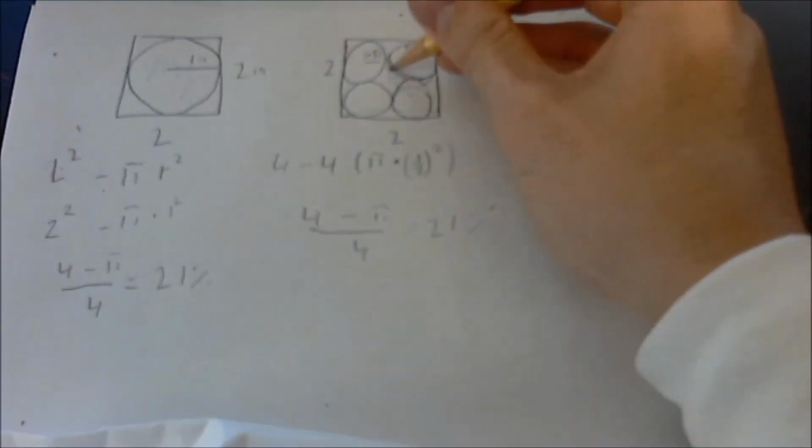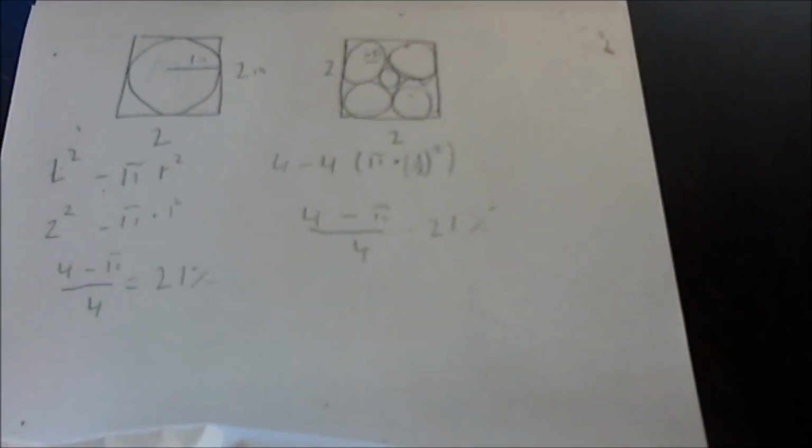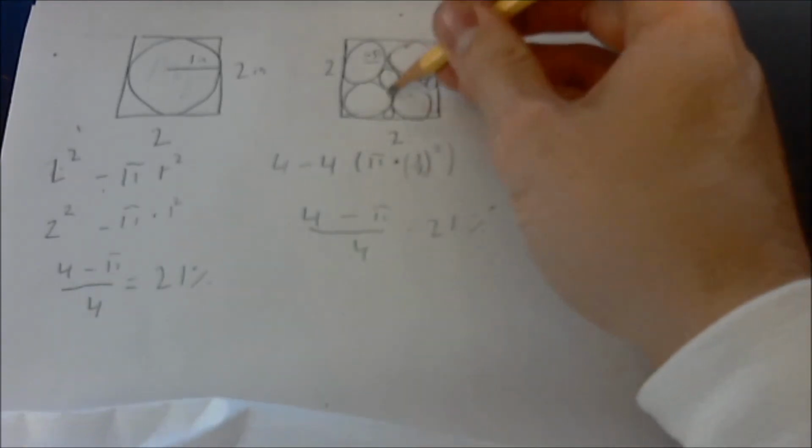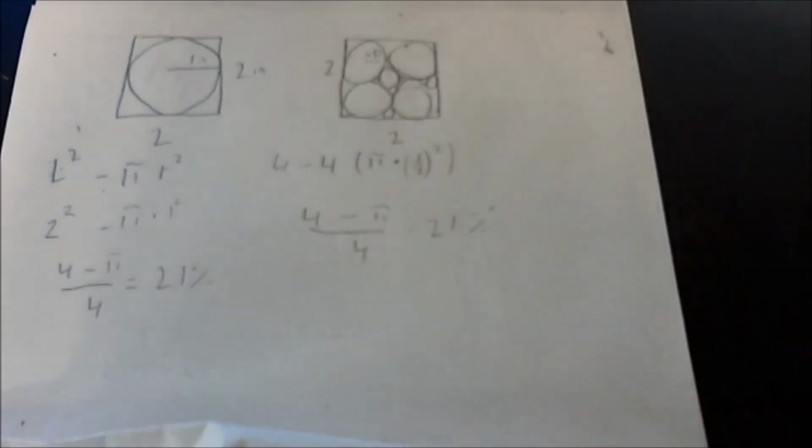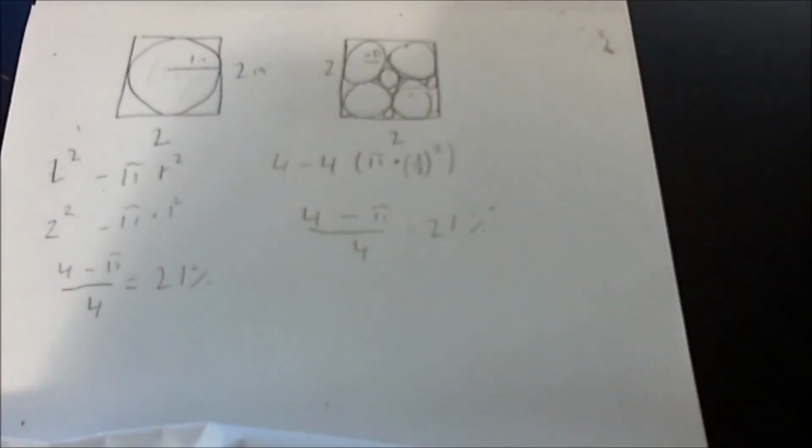So if you imagine, though, if I filled in this area with a smaller rock, and this area with a smaller rock, and this area, and this area, and this area, eventually we have no area left. So what you do in your analysis is you crush up a sample of rock, and then you find the distribution of the grain sizes, and from that you can figure out mathematically what the porosity is using a similar process as this.